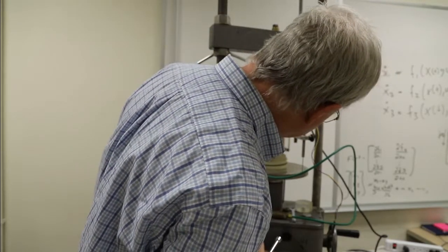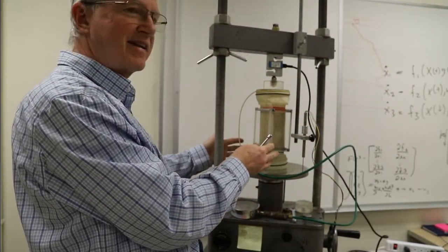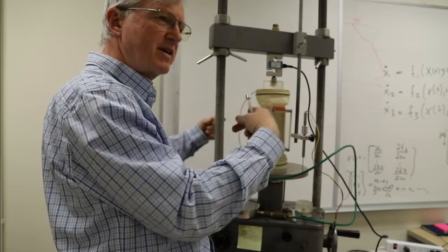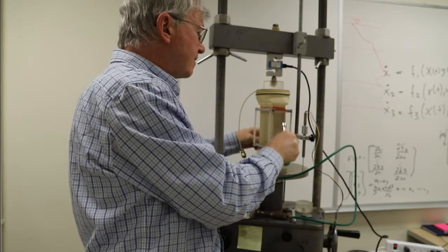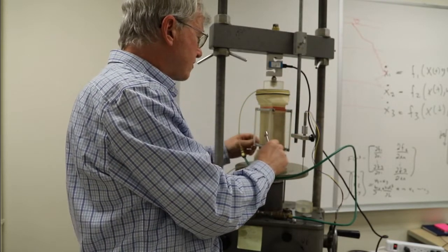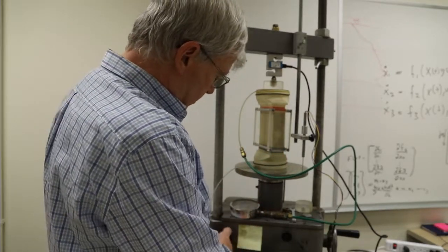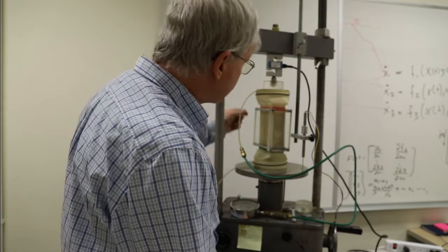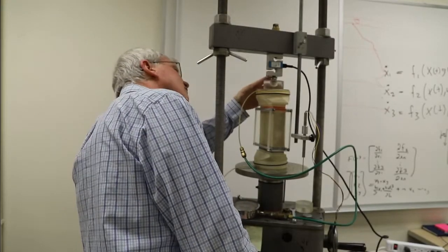And we want these plates on kind of snug. If they're too loose, they just slide down on the grease. But we also don't want to pre-squeeze the specimen much in the epsilon 2 direction either. So this looks pretty good. Alright, so we're going to bring the specimen up a little closer, and we think it's level, and we think it's centered. Both of those are important.